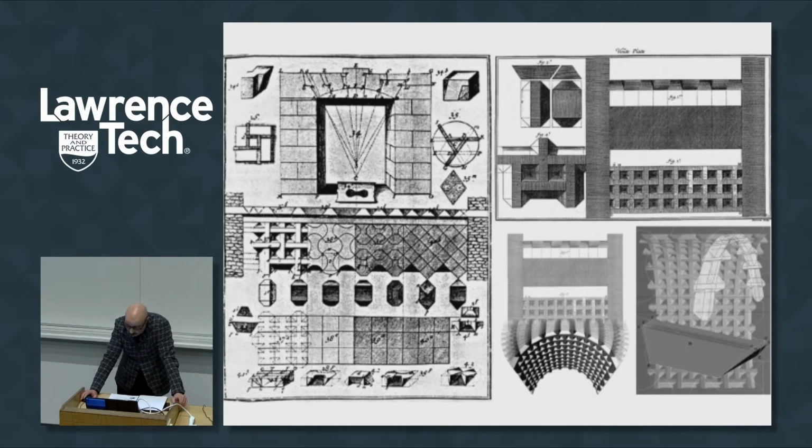The static behavior of such a solution is the same as a bidirectional slab floor structural system, working identically in both directions. Each of the ashlars is supported in such a way that the vault is working only after completion. Such static conditions allow us to consider such a structure as belonging to the structures called reciprocal frame structures.